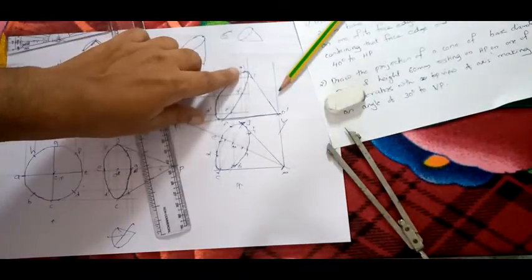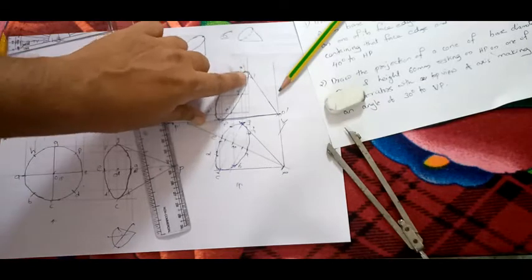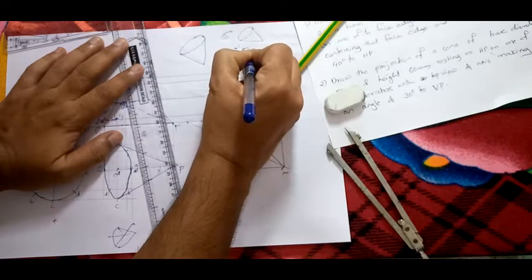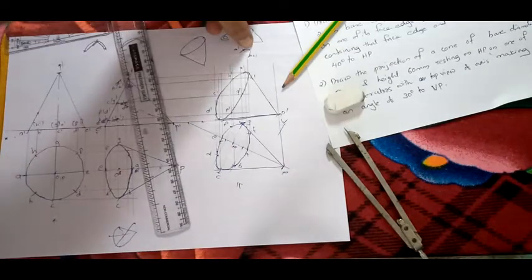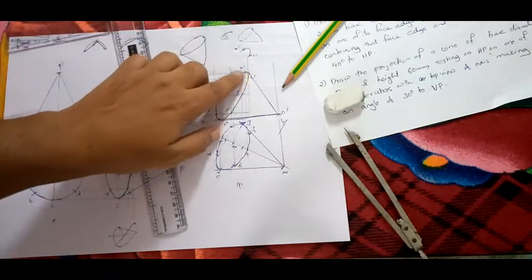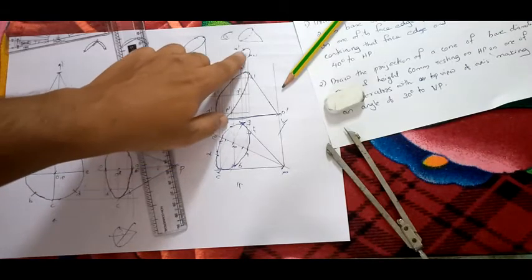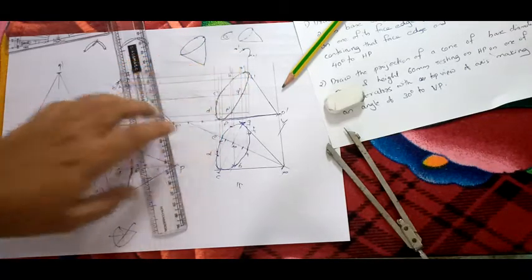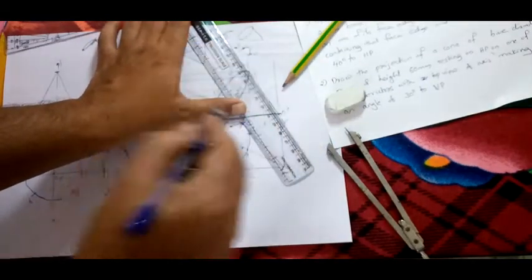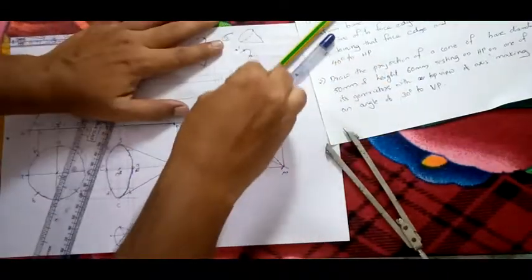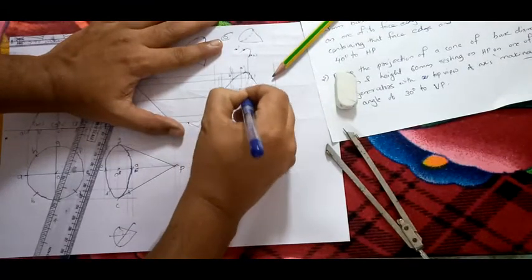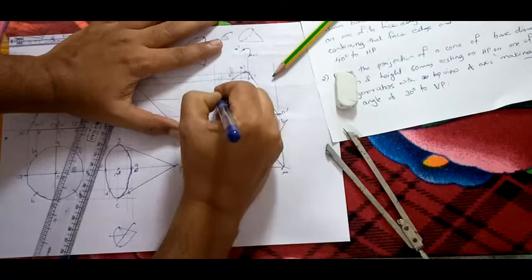Here there is a problem. The outermost point will be in between A and H. See, here your A dash will be like this and H dash will be like this. If you extend the figure, you will get like this. See, this will be your extreme point. This will be your extreme point. So kindly note the extreme point here is not A dash or H dash. It is some other point. So for finding that, you have to fix the pen here, then rotate like this and find the outermost point. Now what I next do is rub this off, then make this dotted. This portion make it dotted, and this will actually be visible.